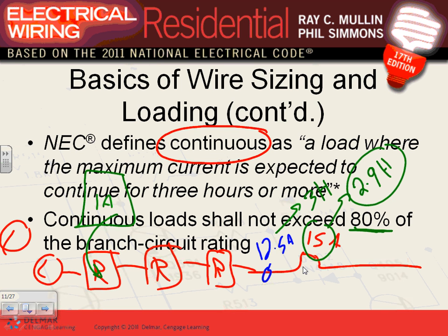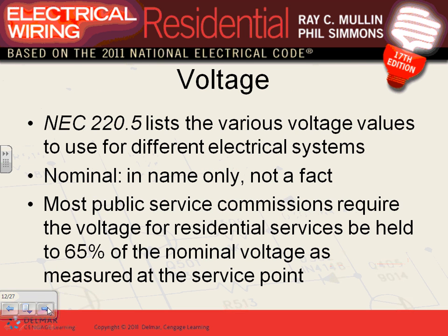And when they say the circuit is 100 amp, what does circuit 100 amp mean? The overcurrent device ahead of it is 100 amp. Any questions about continuous load? Actually, for all practical reasons, residential loads are non-continuous. Because yeah, you have a plasma TV on, but you turn everything off in the process.